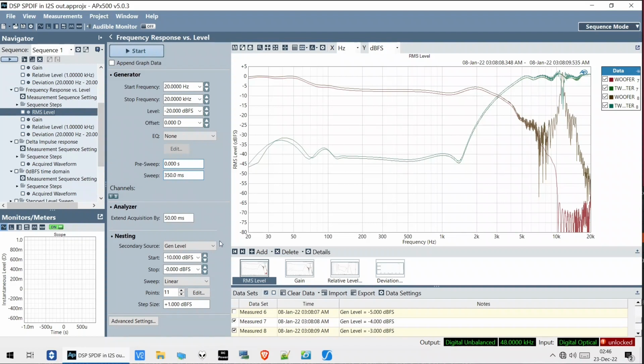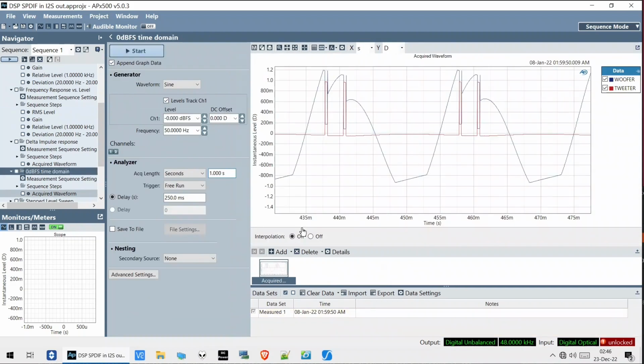So now this whole expensive measurement machine is just turned into an oscilloscope. But look at this. This is supposed to be a sine wave. So if we're looking at the woofer here, I think it's a 50 Hz sine wave. This is not exactly round, but it still has the right periodicity. And here we see the absolute carnage that's going on. The signal is going over 1.0 FS, so over full scale. And after that, it's anybody's guess.